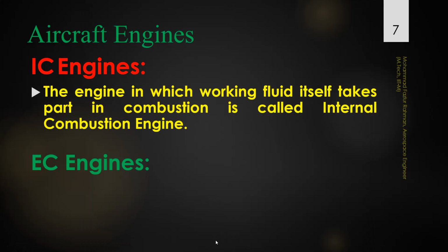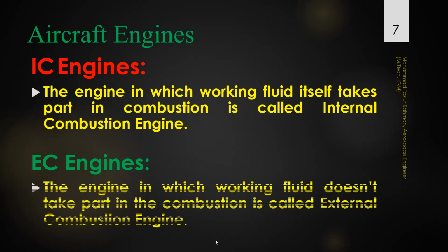A new definition for IC engine and EC engine is that an engine in which the working fluid itself takes part in combustion is called an internal combustion engine. Similarly, the EC engine is the engine in which the working fluid does not take part in the combustion, called an external combustion engine. This definition is more consistent and gives a good idea about the differences between these two engines, because even in an EC engine, when you say external combustion engine, it doesn't mean that we do the combustion somewhere outside and then bring it back inside the engine.